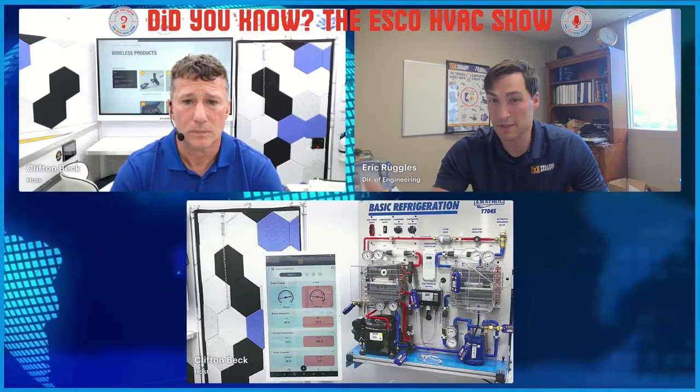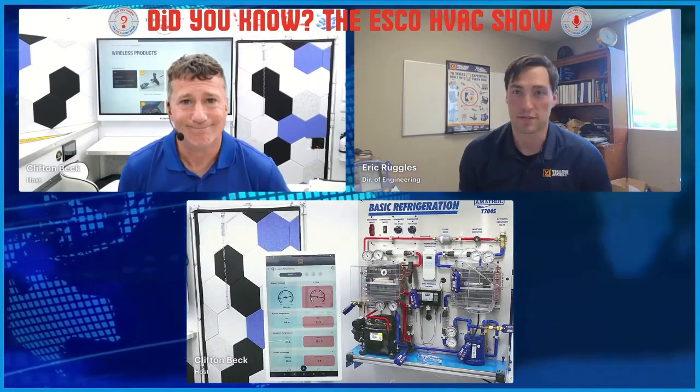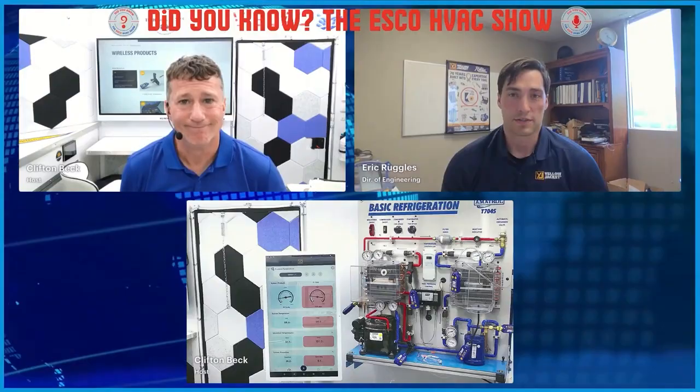Yep. So the amp clamp, again, measures your compressor amps, your fan amps. I think that's critical when you're trying to figure out if there's a problem in the system, whether it's refrigerant side or air side. You can really tell a lot by understanding if the motor's running to rated load amps or not. If your compressor amps are supposed to be 12.5 and it's only running at 7, there's probably a problem with the refrigerant side of the system. If your fan amps are supposed to be running at 4.5 or whatever, and it's only pulling 2 amps, there's probably some sort of air side issue, whether it's with the fan or a restriction in the duct, dirty filters, etc. That's something you need to think about.